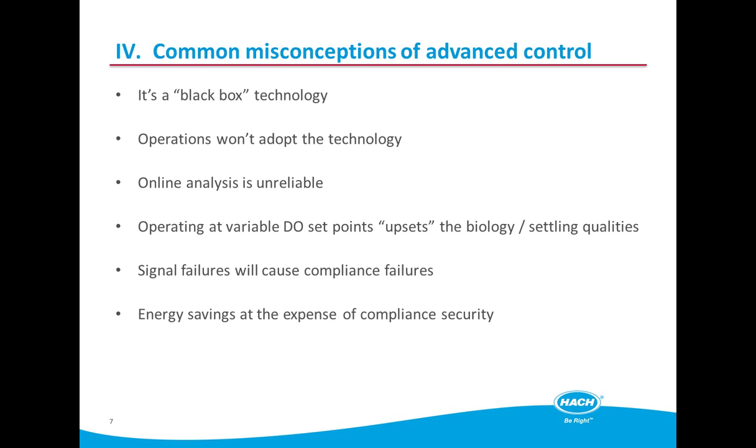Large advances have been made with online analysis and, importantly, the filtration systems that enable the sample to be presented to the analyzer. We have systems that have been successfully in operation for many years, providing valuable process information, compliance security, and energy savings. There are some schools of thought that using variable DO set points upsets the biology or settling qualities of the mixed liquors. This is simply not true. We have nitrification-denitrification systems that use a period of 0 DO with perfectly healthy activated sludge biology.